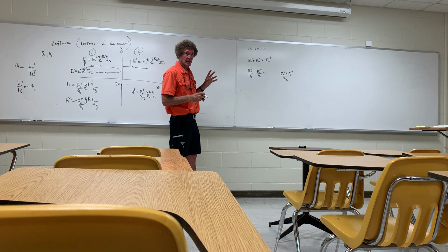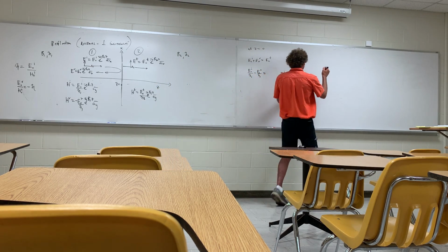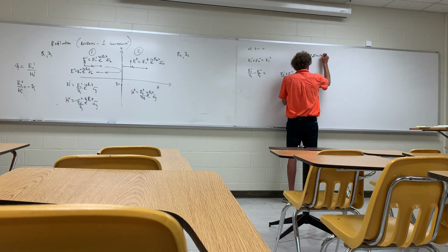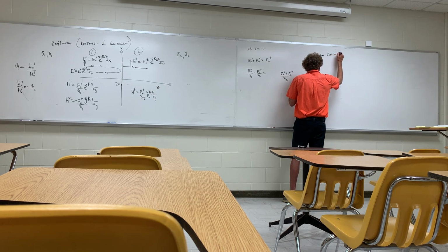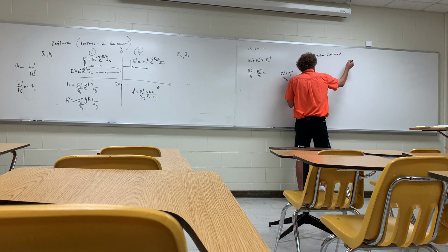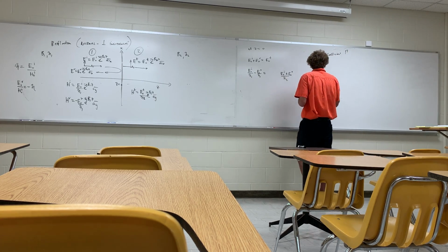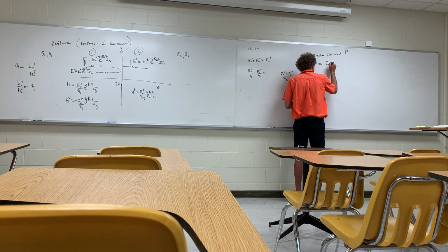Okay. Now what I'm going to do is simply divide. I'm going to create a new constant, and this is the reflection coefficient. The symbol is given as this, same as it was with transmission line theory. We define the reflection coefficient as the reflected field's magnitude, E naught reflected, over E naught incident.